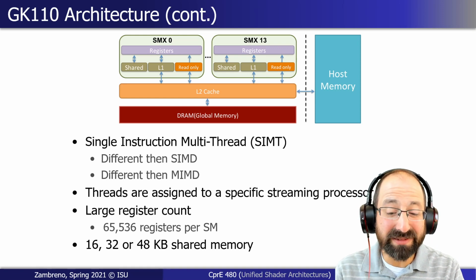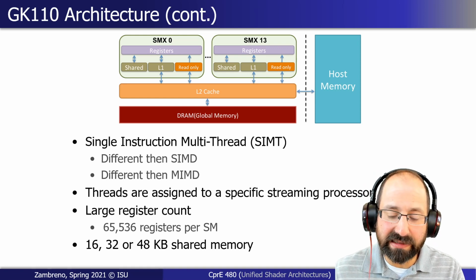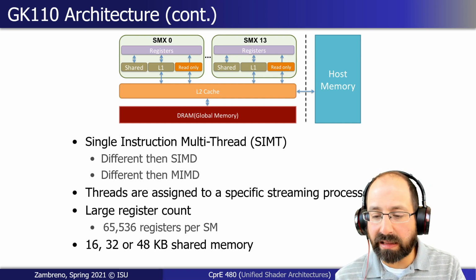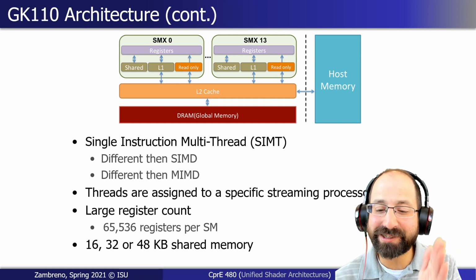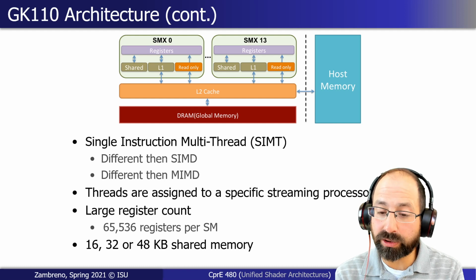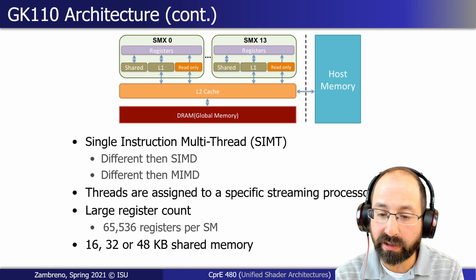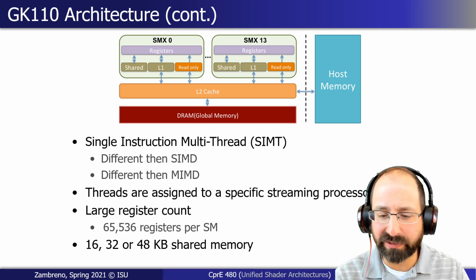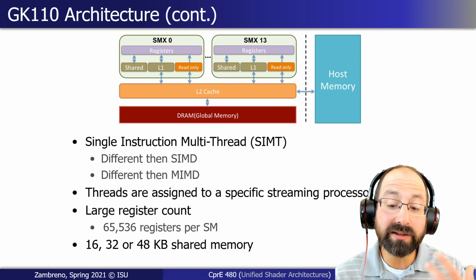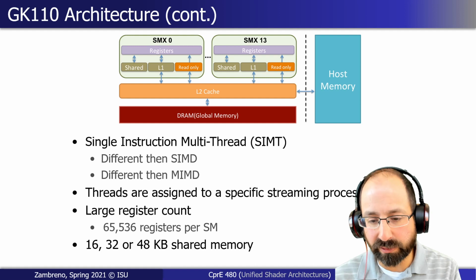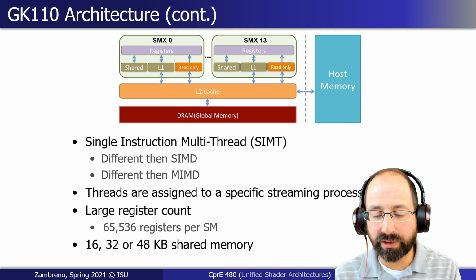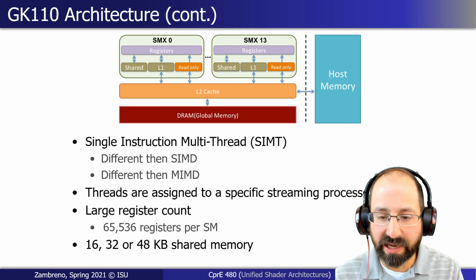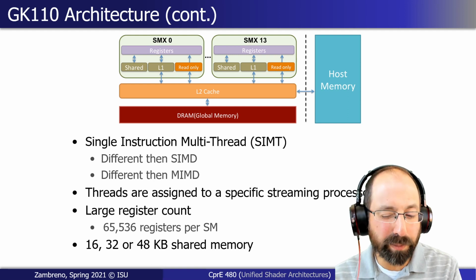We also talk a decent amount in 381 about SIMD as a microarchitectural optimization that allows for a certain level of parallelism. That is single instruction, multiple data. That's what our cores, at least in theory, in 480 this semester are implementing. Very similar to a vector processor, though there's a subtle distinction between a vector processor and a SIMD processor in terms of instruction streams. In general, you have a single instruction at a time from a single thread of instructions, executing on a block of data at a time, where the block tends to be pretty small.